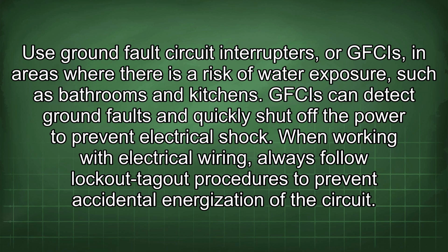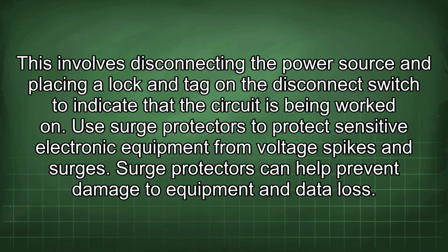When working with electrical wiring, always follow lockout-tagout procedures to prevent accidental energization of the circuit. This involves disconnecting the power source and placing a lock and tag on the disconnect switch to indicate that the circuit is being worked on.